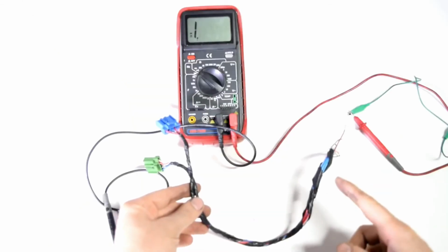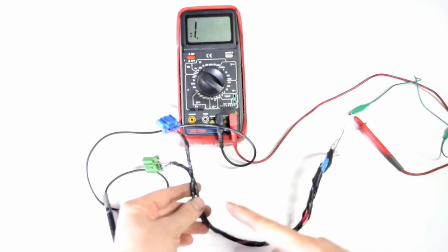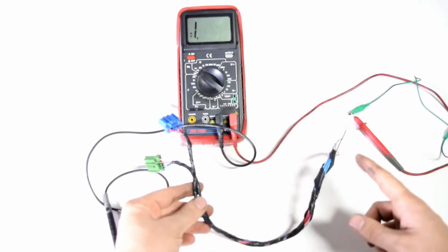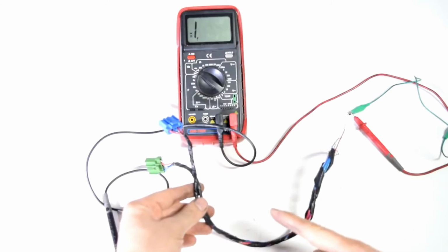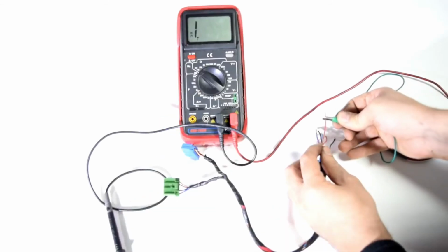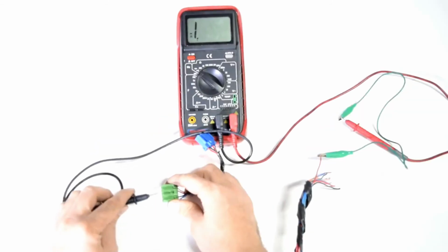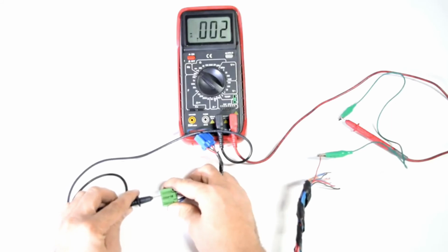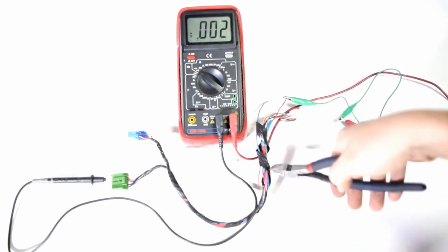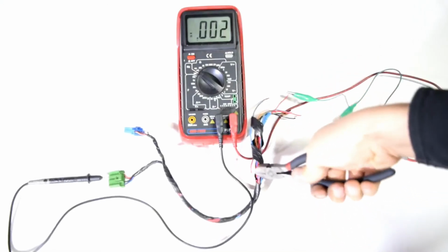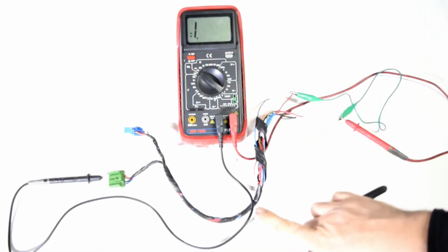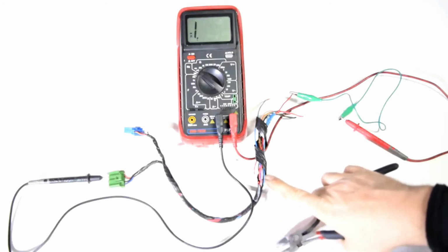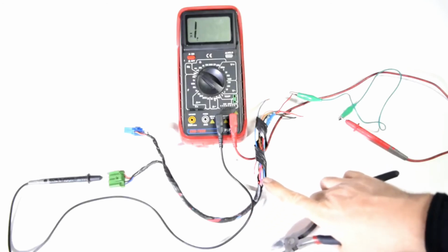So for example, if you wanted to make sure the wires that go to this connector are in good shape and that electricity or current can travel through them, you would attach one of your test leads to one end, and then your other test lead to the corresponding pin on the connector. And if you hear that beep, that means you got continuity. And if you do this and you don't hear a beep, it means that you got a short somewhere in this wire, or in other words, in our case, maybe a cut or burnt wire.